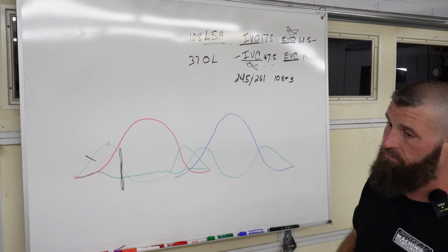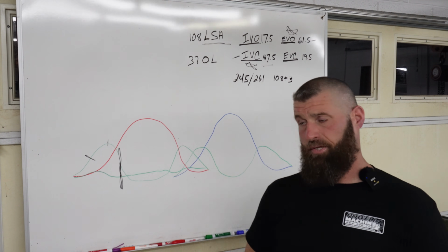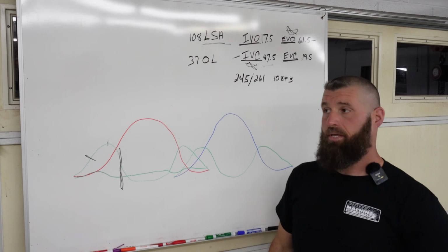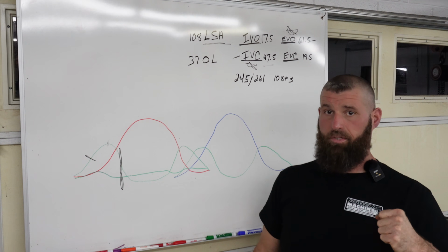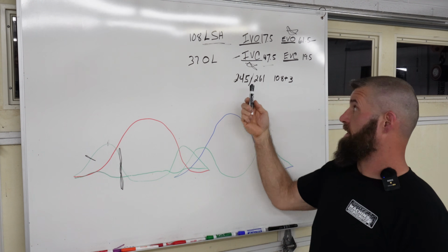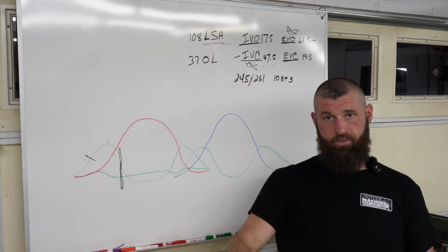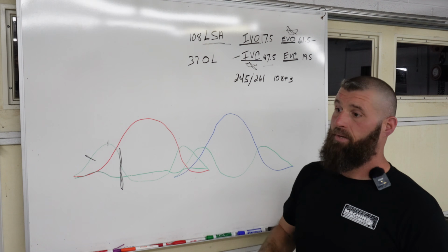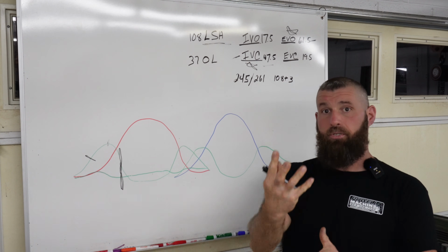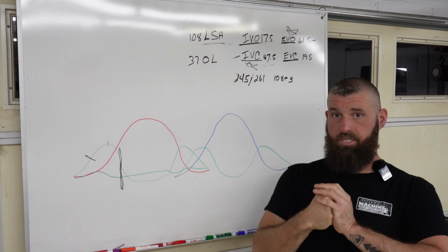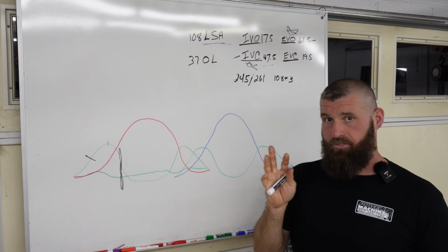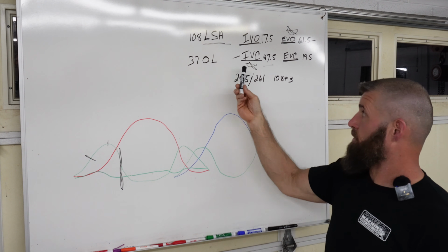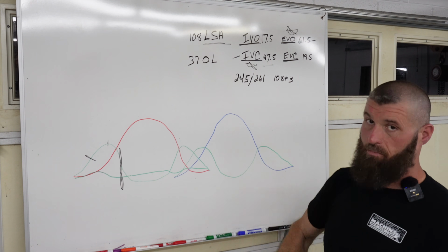So with the intake valve closing, a couple of things. So one, at low RPM, we're going to trap less in the cylinder because this is happening as the piston's coming up. So this happens before TDC. So the piston's coming up and it's trying to push whatever's in the cylinder back into the intake. That's a problem at low RPM.